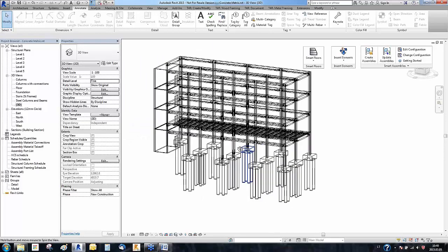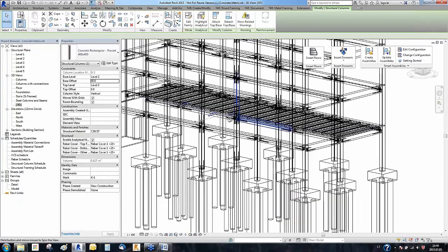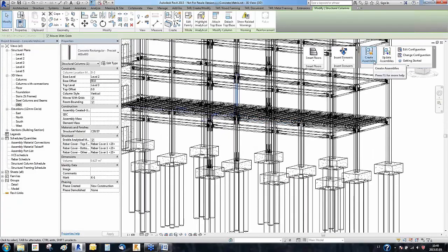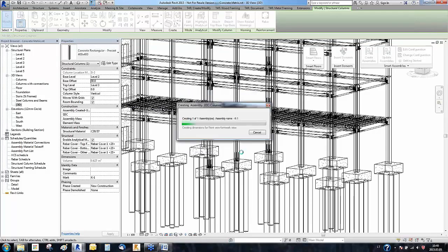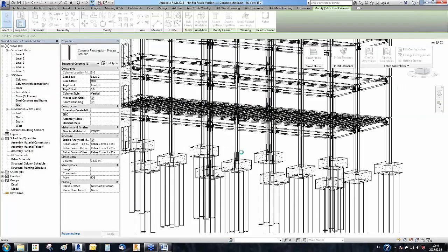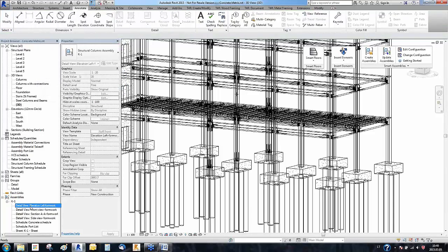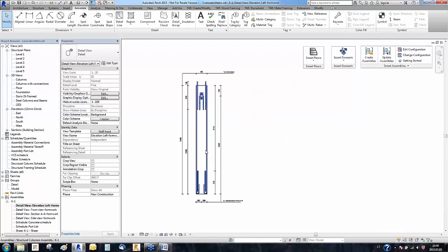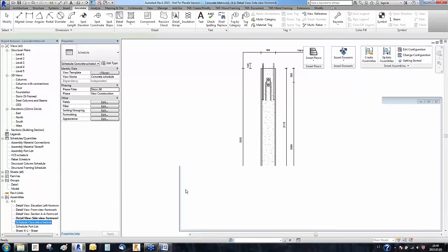And now I will also run through smart assemblies quickly. Let's say I will select one column. I will create an assembly with our tool. I will select the right configuration, and I will do OK to create. Okay, and we have one more drawing here with all our elements inserted. We will have views defined, and we will have